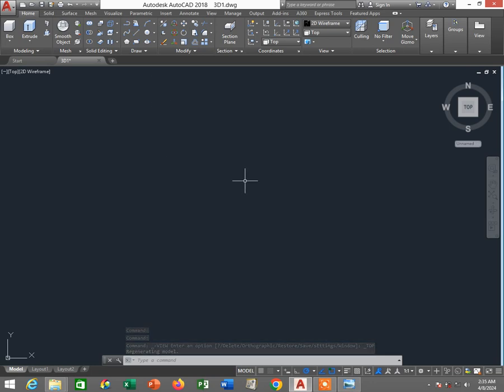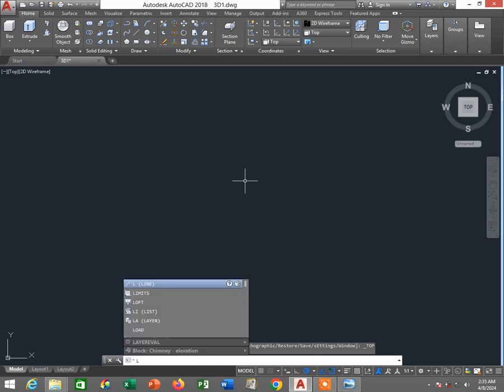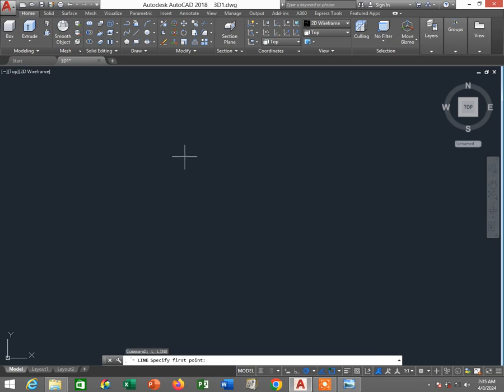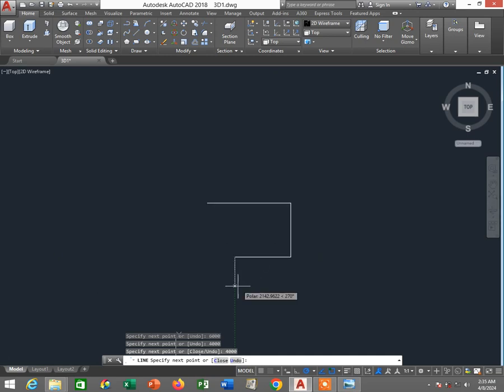So I just type L, enter, and start to draw the floor plan. I click and use polar track. I'll take the dimension over here, maybe around 6,000, yeah, 6 meter. For the porch area over here, I'll take around 4 meter or 4,000, enter. This one going in like this, 4,000, enter. This one also 4,000. Okay, press enter.